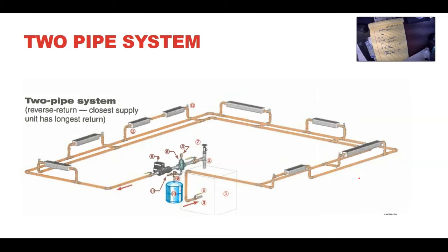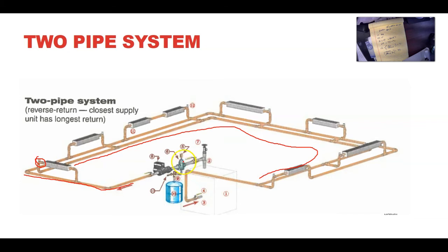So the two pipe system, which is the best, most elegant way to distribute heat through more than one room. And again, in this case, we still do have valves for prioritizing, and we have a valve to dictate how much water goes to each pipe. And that's a really good way to put it. And we have one hot pipe and one manifold for cold water. So this is a two pipe system where the water goes to each load equally. So this is kind of similar to connecting loads in parallel than in series. So I'll give you a second to look at it, see the difference.